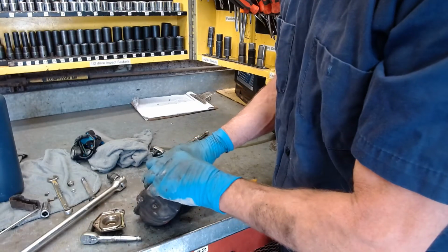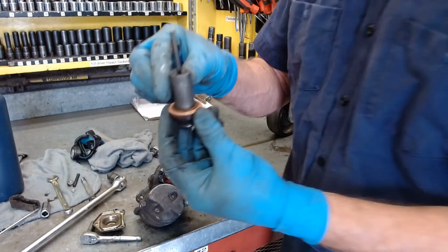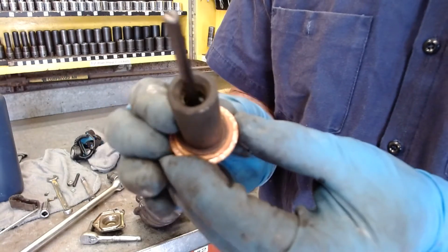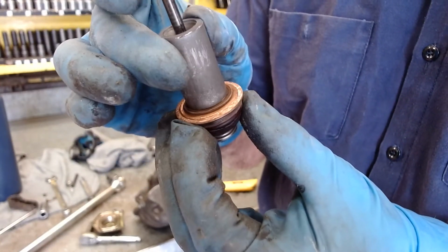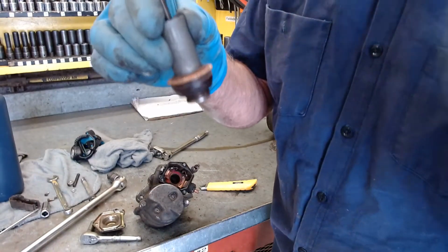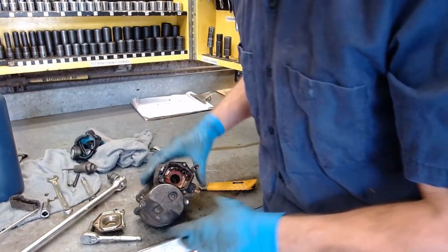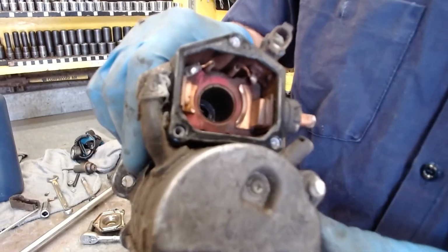And inside here is the plunger that gets sucked down in the solenoid. And what happens on these usually is this corrosion right here. Let me see if I can get it to focus. Yeah, there it goes. You see all the corrosion on the edge there. And that has got a pretty good step in it. So it's corroded pretty bad. And those contact on these two metal contacts down inside the starter.